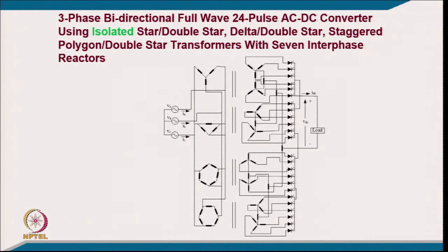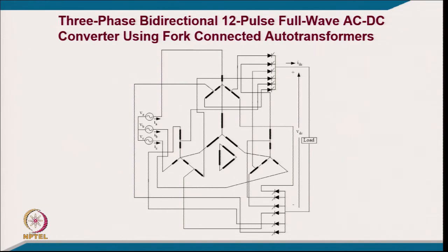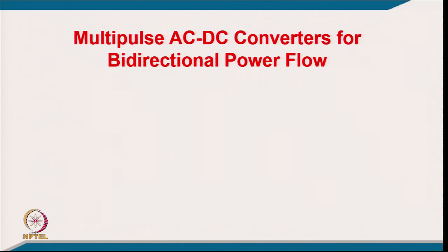And another is typically 24 pulse. So, you are converting 3 phase supply into 24 phase supply, and then you are using a thyristor converter for controlling. Full wave converter, only one thyristor comes in the path of the current, and you are able to get 24 pulse in the output. You get control of voltage, but at the cost of reactive power burden, but harmonics are certainly reduced corresponding to 24 pulse. And this is again another connection of 12 pulse with the full wave, non-isolated category.